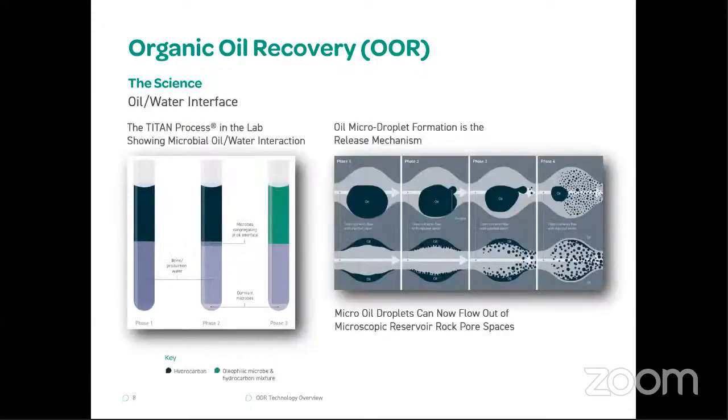So basically, this is the science of how this microbe works, how this OOR can help to recover the trapped oil, or the oil which we call the residual oil. If we see the first test tube, we took some water and oil in a separation phase, and actually the microbes naturally are in the water phase 99.9% of the time. They like water, which is called hydrophilic.